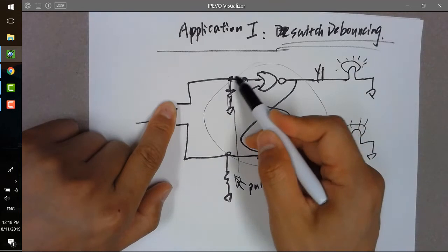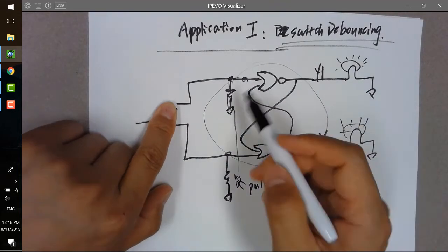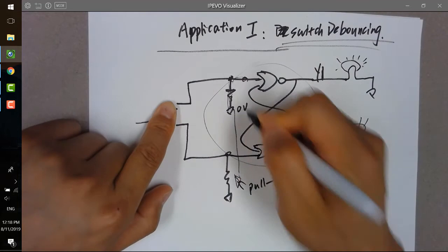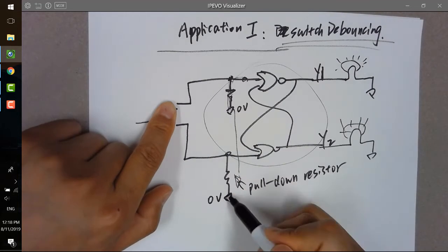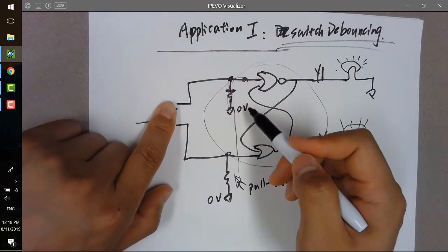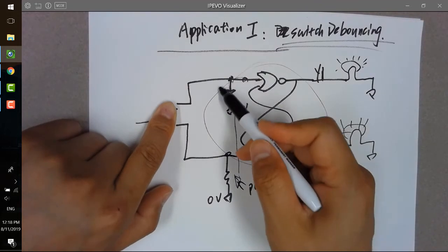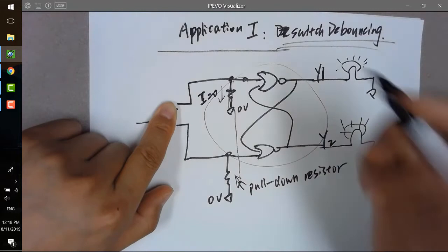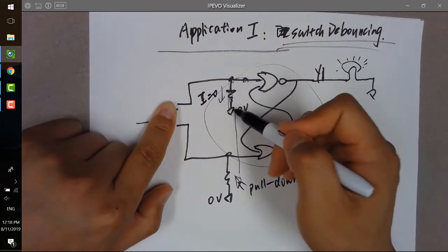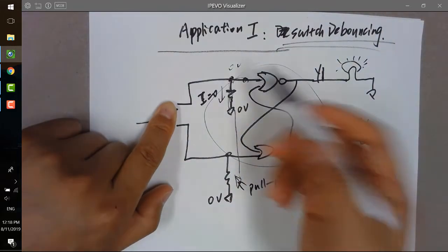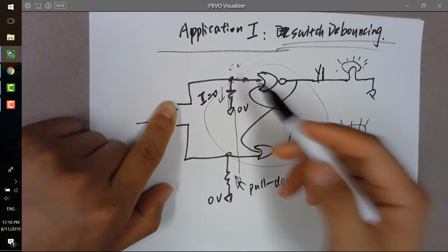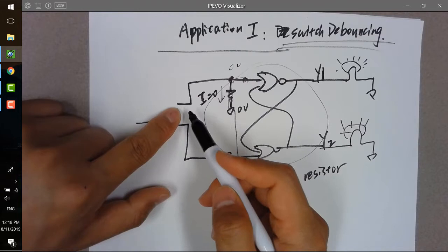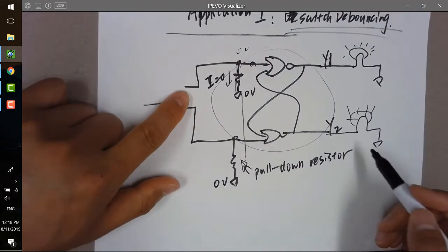You have this pin grounded, which means you are applying a pretty strong 0 volts source here, which is a ground. Since there's no current flow through the circuit, I equals 0. No current, no voltage drop, so 0 volts here, 0 volts here, right? So that's how you can give a pretty solid 0 to the circuit when you have nothing connected to the input here. And this will be pretty useful, remember that.